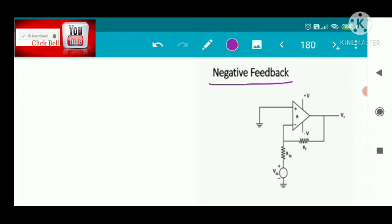So for negative feedback, you can see the feedback resistance is connected to the negative terminal, that means the inverting terminal. Also this is an inverting amplifier, because we have given the input to the inverting input and grounded the non-inverting input. This is the supply voltage plus B and minus B. Hope the circuit is clear to you. Now the feedback signal should be subtracted from the input signal, so that it is negative feedback. So your error signal must be Vin minus VF.